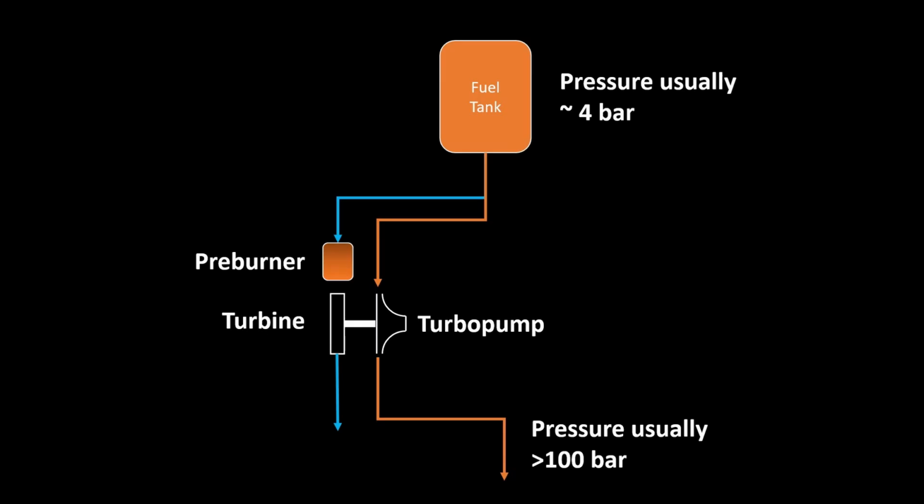And those turbopumps are powered by a turbine wheel which is positioned in the exhaust trail of the preburner. It's basically a small rocket engine inside the actual engine. But there is a major problem involving the preburners. To start the preburners and therefore the turbopumps, the fuel must already be pressurized. That means turbopumps have to be running for the preburners to work, but the turbopumps need the exhaust of the preburners to spin, but the preburners need the turbopumps to run, which require working preburners. Damn, we are in an infinite loop of something requiring something else to work, and without any external help, the rocket engine would be unable to start.